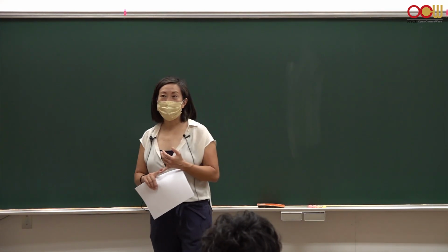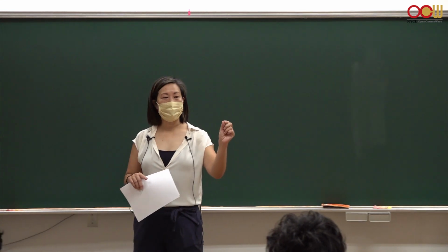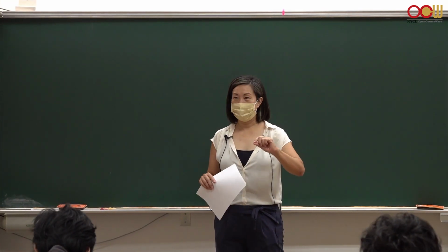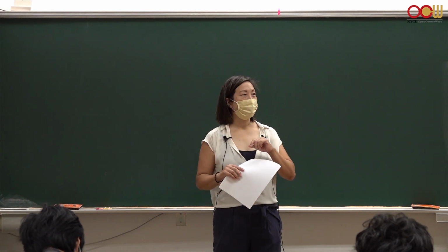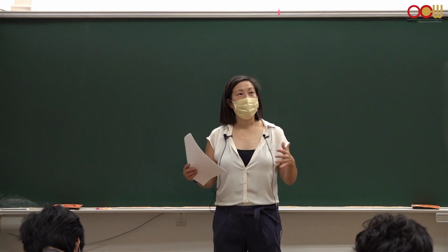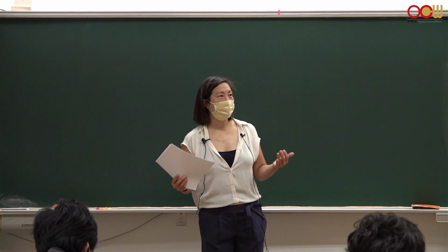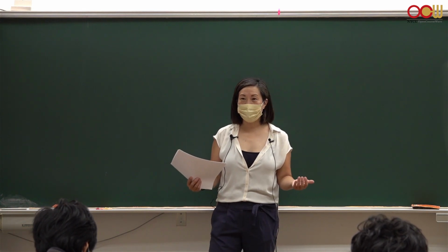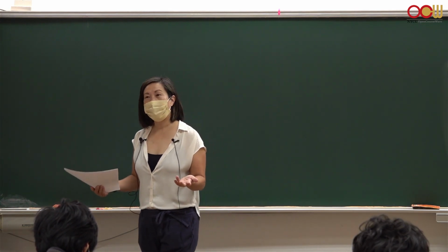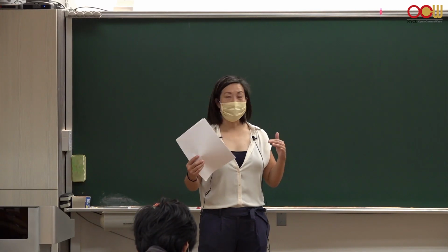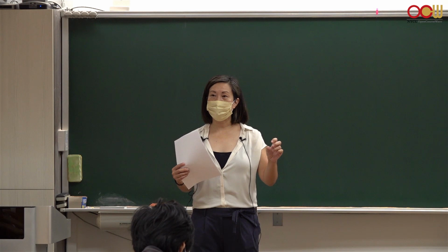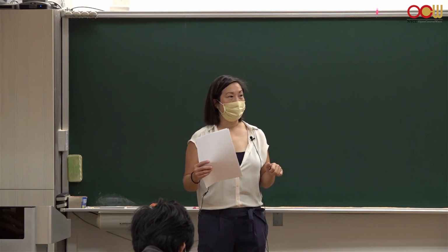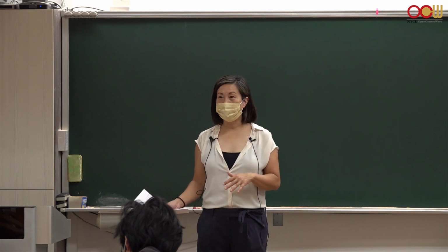So in order for slip to occur, you have to be able to break individual bonds and form new bonds. We know that in ceramic materials, this is not usually possible because the bonds in the ceramic material are either covalent or ionic and covalent, and they're very, very strong. So it takes a lot of force to break it, but once it's broken, because of the localized electrons, it is very difficult to reform. Okay, so ceramic materials are usually brittle.